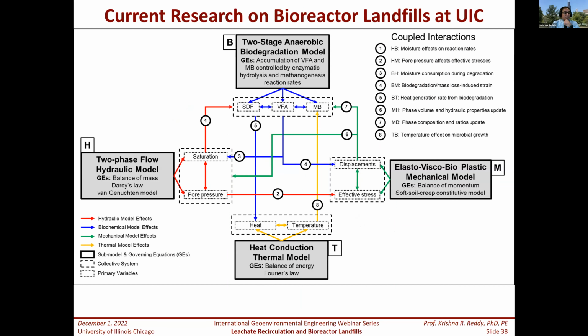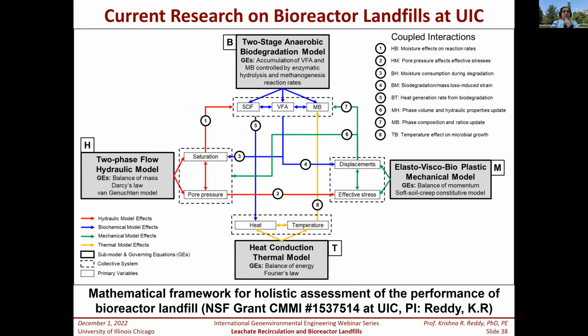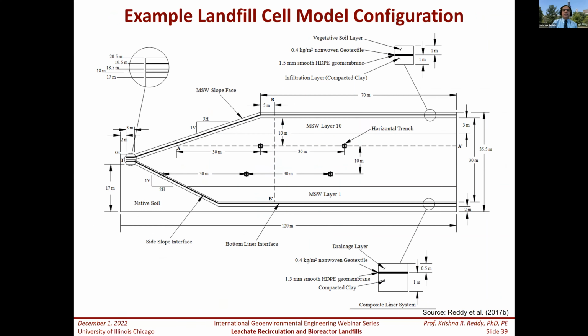So it's very complicated. So in our research, we had a National Science Foundation project, and my student Girish Kumar, he graduated a couple of years ago. He developed this coupled thermo-bio-hydromechanical model. So you can have a biodegradation model here, and then you have a flow model here, a thermal model here, and then you have a mechanical model. So they all need to be coupled, right? One fits into the other one.